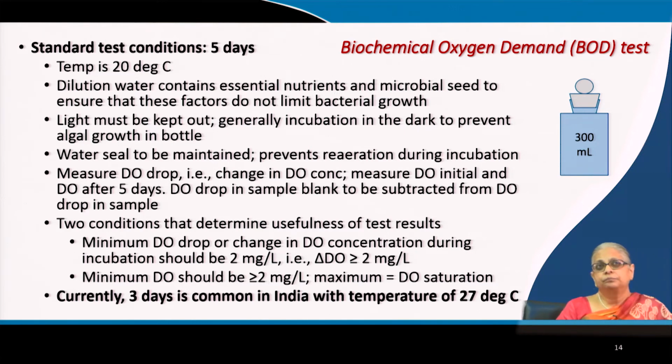And these 5-day results correspond to about 60 to 70% of the entire biodegradable fraction of the wastewater content. So the 3-day at 27 degrees centigrade is expected to give similar results.